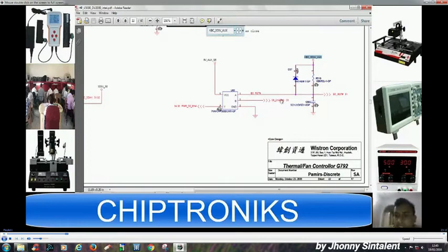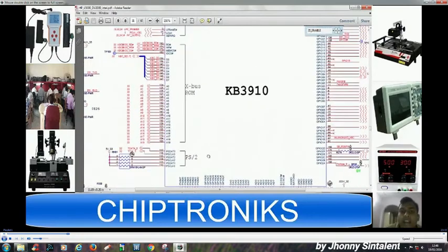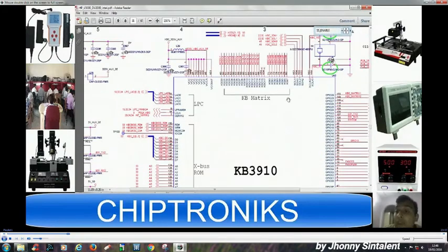Now A is there, we have to check B. So if A and B are there, then Y would come. Now A is 3.3 volt and we have to check the S5_enable. We'll go and see where S5_enable is coming from. Now this is written on page number 31. So S5_enable is the output of the IO controller, and when would this IO controller give output? When it gets its important inputs.